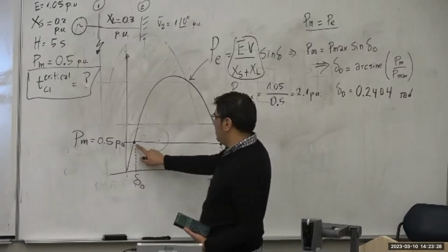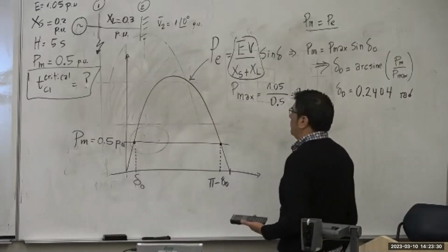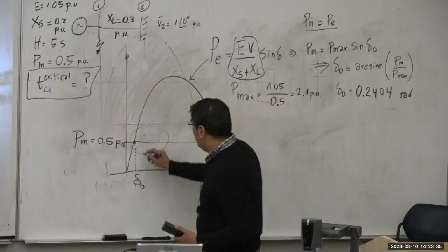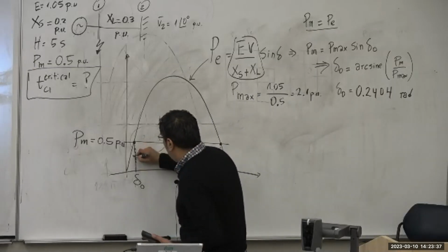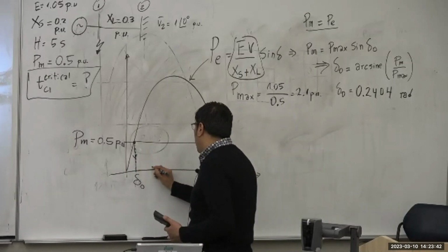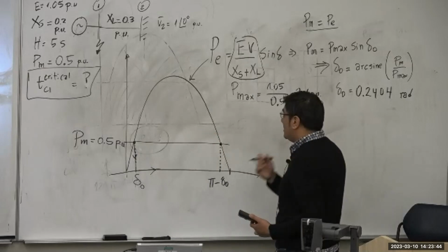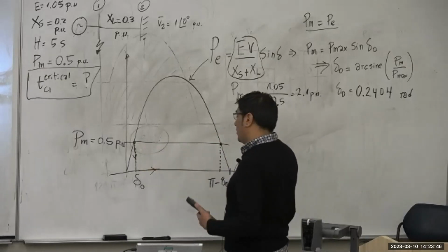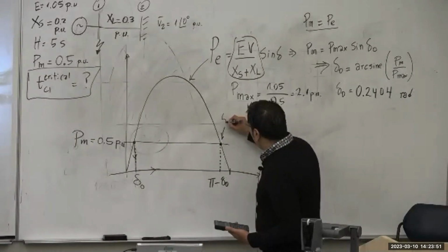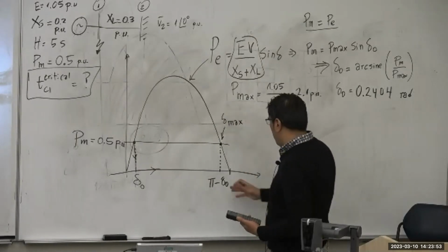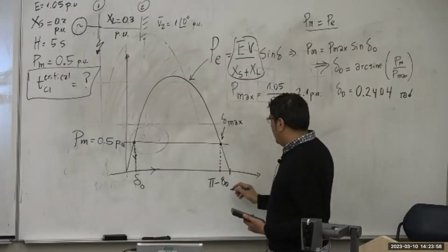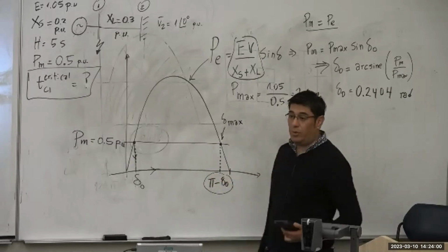But the system starts here. The system is at the equilibrium point. So when we clear the fault, then the power immediately is sent to 0. The speed and the angle will increase because we will have a positive accelerating power. But we want the maximum angle to reach the maximum possible angle before we lose stability, which is at this point, the saddle node.